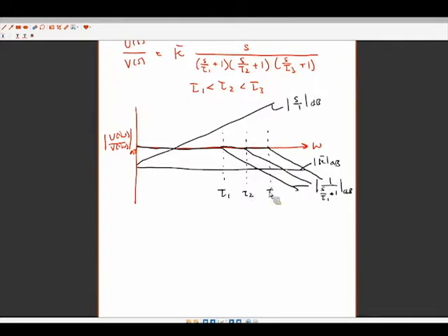Okay, so getting back to your point, if this happened to be the case where we had complex conjugate poles, that would mean that we still have one of these, say, for instance, the one at tau 1, and then each of these individually contribute negative 20 dB per decade slope, right? The complex conjugate pole after the break is going to have negative 40, and then a resonance peak. We don't have a resonance here. Yes? Ben?